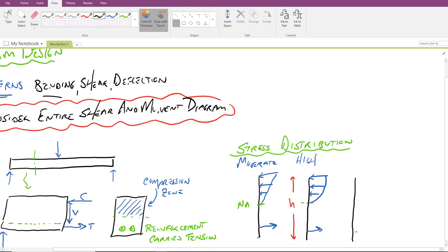As I've indicated in other lessons, generally speaking, when we have curve type shapes, they become difficult to explain mathematically, and so we try to simplify those as best as possible. So we'll keep our neutral axis here in the middle. And if we could approximate this same area that exists in the compression zone for a high load as a rectangular shape, that would make life a lot easier.